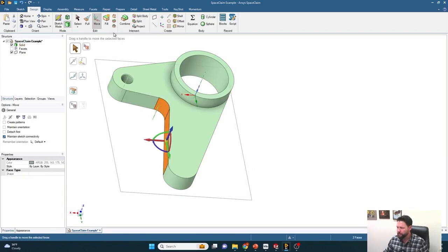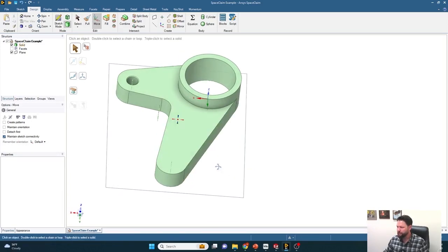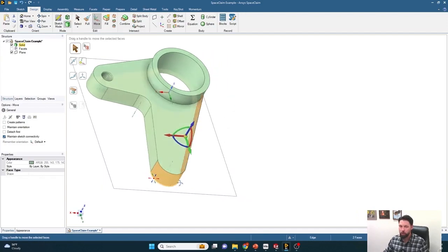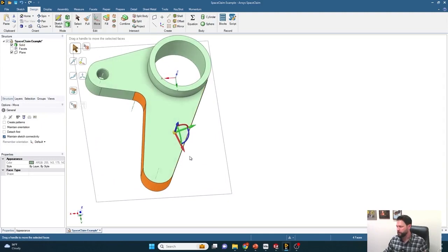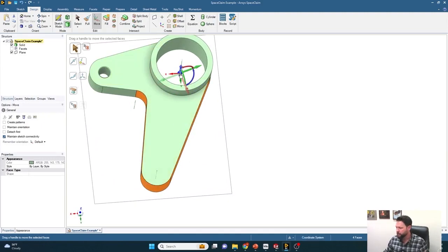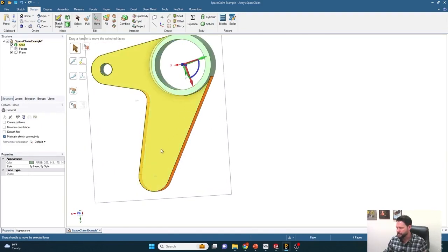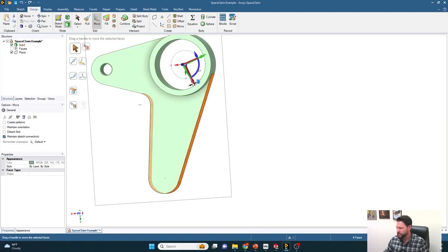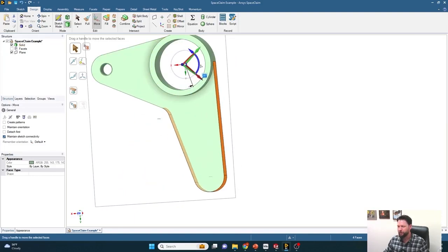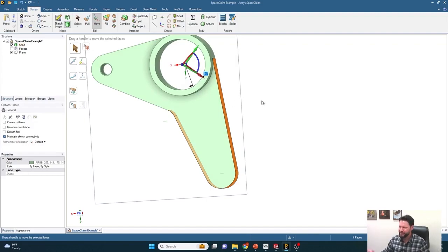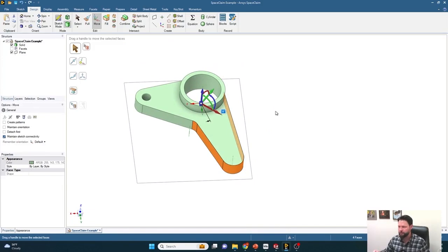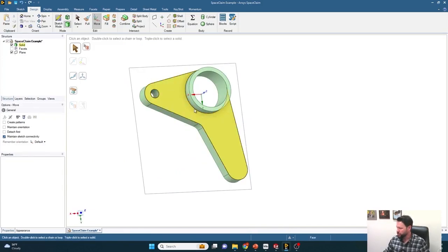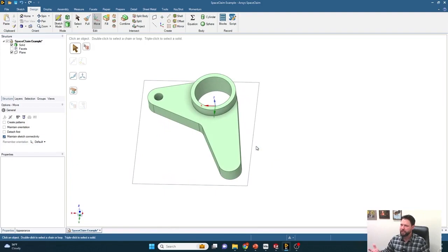You can grab using this move tool, instead of going back and changing your sketch and then hoping that sketch doesn't crash the model and all that you normally see in a parametric file. I'm going to anchor this move tool to my center axis. I'm going to click those side surfaces, and then I can rotate that part. So it's awesome. I mean, you just can't do that quickly in any other program or any other type of modeling program. So you can adjust that angle, and you can make a completely new part based off of the one that we reverse engineered.